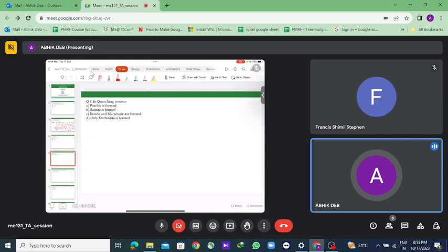Okay, so coming to the next problem. Okay, sir. During continuous cooling at just less than the critical cooling rate till the 50% transformation line, followed by rapid cooling, results in which of these? So you have to know the continuous cooling diagram for this. Suppose this is time, this is temperature, and suppose these are the two transformation lines.